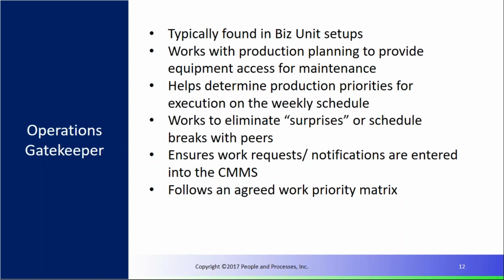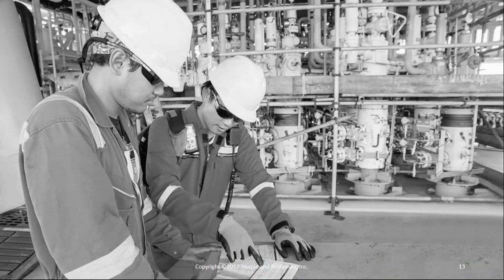And what we should have is one centralized, one standardized priority matrix. So 1 is an emergency, 2 is urgent, 3 becomes PMs, for example. 4 is the first level of category, if you will, of plan work. 5 might be the next category, lower priority, and 6 might be the category after that. So you notice I just said that there were 3 separate categories for plan work. And there's some reasons for that, but we won't really have time to address that in this session. So now let's talk about the supervision aspects.